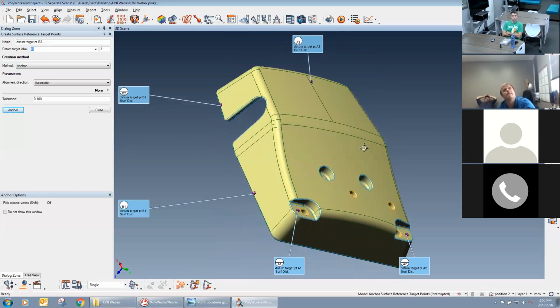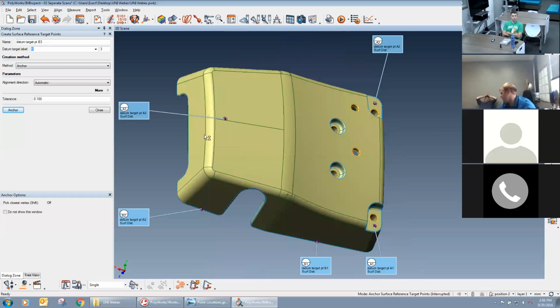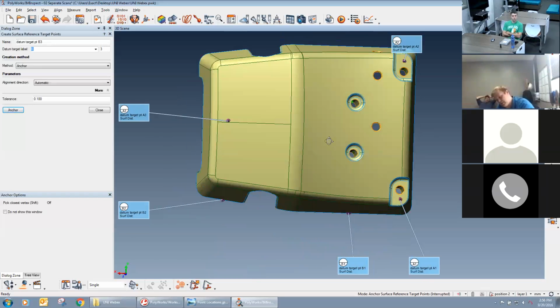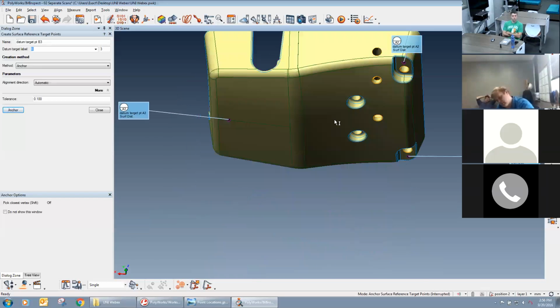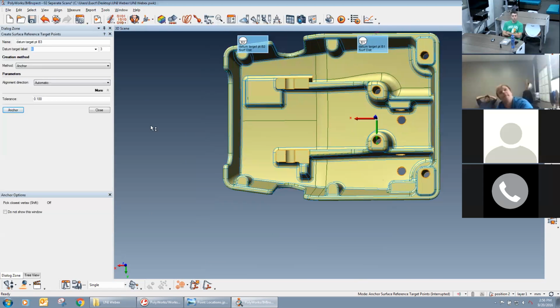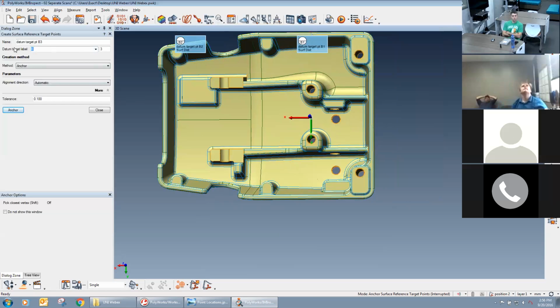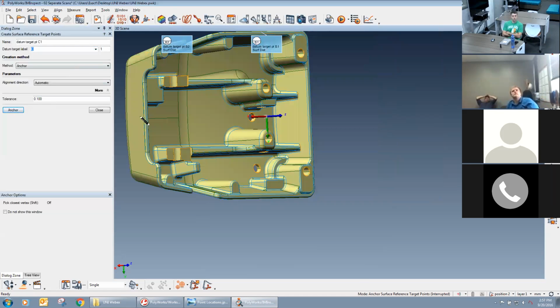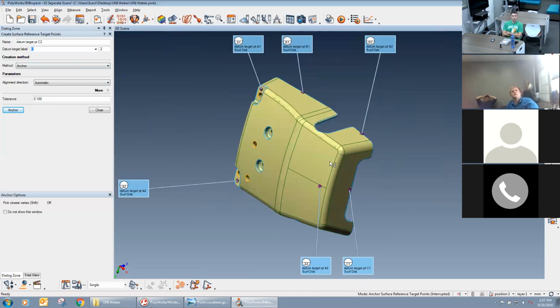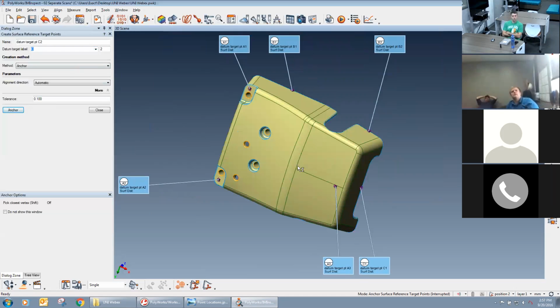And then lastly, I have to pick my C datum, which would lock in my X direction. So they would set on all 3 A's, and then it would be pushed up against both B's, and then it needs pushed back against a C datum. So datum target label, I'll go ahead and label that as a C, click anchor, and then I'll pick it right here in the back. So now I have my 6 locators picked off of the CAD model.